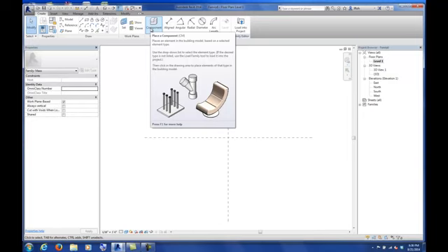Now, what we're going to do here is if you just go back and select that circle that you drew, you'll notice that there's this blue dimension. In Revit, every time we draw, you're going to start to notice these blue dimensions pop up. And they only pop up when you select an item. So when I go back and select the circle, it's there. And when I deselect it, it goes away. Those are called temporary dimensions.